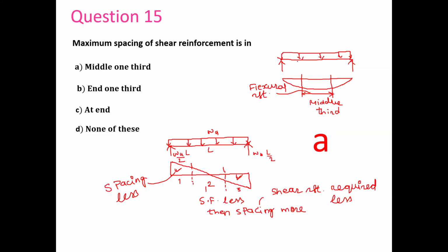in the middle one third. And therefore in beams, we are going to curtail the bars and take bars in this way. Alternately, one bar we are going to bend at the left support, another we are going to bend at the right support, because bending moment towards the support reduces. Then in a slab, alternate bars are curtailed.